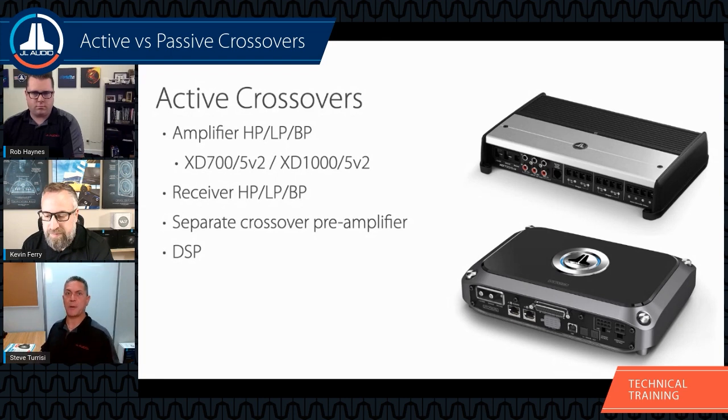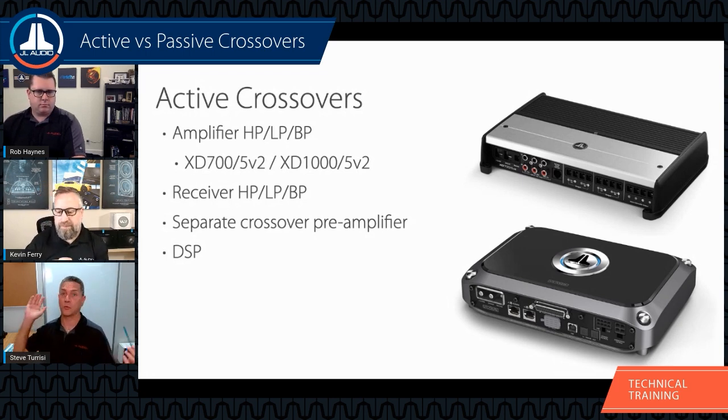Now, when it comes to frequency, it's usually a variable value that you're adjusting in the analog domain. What gets nasty about those things is that over time, some of those parts can go bad, even some high quality ones. And that's why DSP is the way to go. If you have the opportunity to get a DSP in your system, you don't have to worry about degradation over time. You don't have to worry about tolerance drift. You don't have to worry about limitations on what slopes you can use or what frequency. Almost any DSP you're ever likely to use is going to have tons of flexibility and control that you'll never get from another active filter, and you will never, ever see anything even close to it in the passive world. So yes, DSP is the way to go if you can get it into your budget.